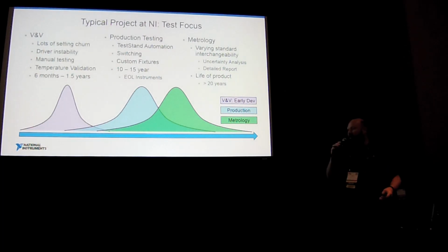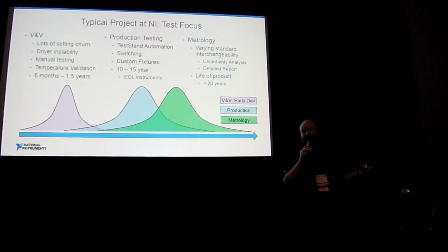Generally, metrology, as an example, some of the challenges they have is when they go to a Cal lab, they're testing a product, and at some point they want to swap out a different Cal standard. Of course, I'm in the RF world, so I'll use some RF examples, but this would be where they want to swap out a different power meter in line of testing, or a different DMM, if you will. And so you're worrying about the uncertainty of the instruments and the measurements.